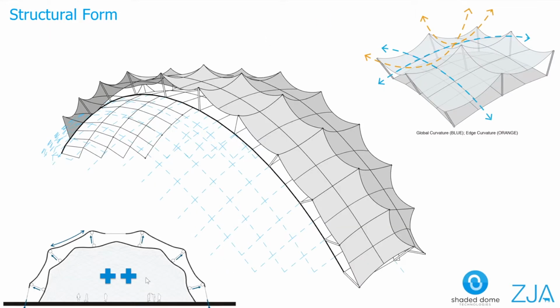Just coming back to some basic fundamental principles. Whenever you talk about a tensile fabric structure, they're generally tensioned and they achieve their structural stability due to their doubly curved surface or anticlastic shapes. Here it is no different in the shaded dome. The global convex curvature, which you see, is the result of the overpressure within the air-supported dome, which is represented by these blue pluses, and the force being transferred to the shade above via spacers is represented by these blue arrows on your left-hand side corner.